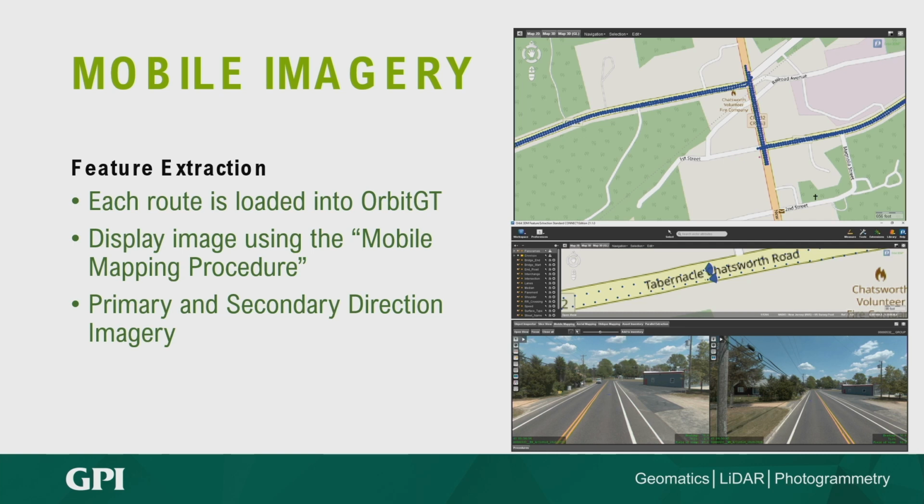So when we're capturing a picture every 5 meters, then you've got all these points along the roadway that's based on the mobile trajectory. So that's the GPS unit with the mobile LiDAR unit. And we can then use this map up here to make sure that we covered everything. We got imagery on all the limits that we need to, and that we can then move on to processing.